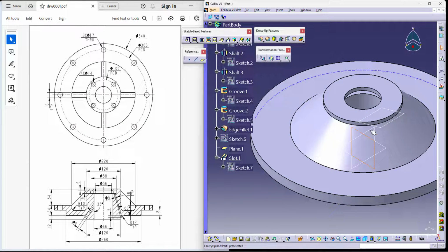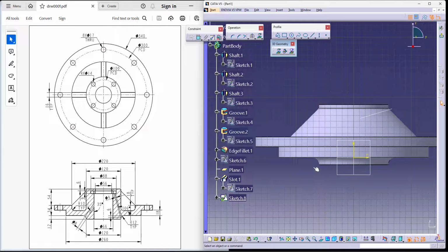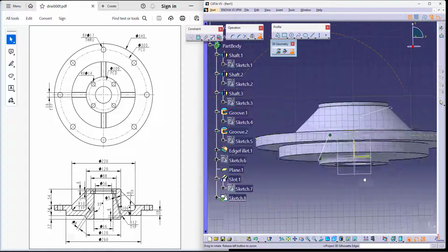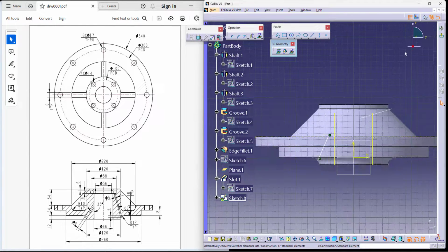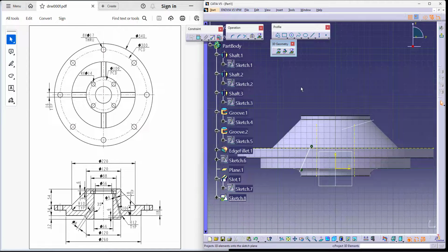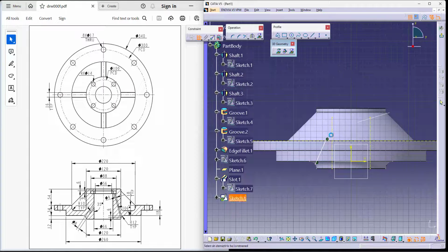Similarly, you have another one on the opposite side as well. You can pretty much do the same thing and go. I'm using my references at the moment. Similarly, I have the top face. It's stopping at the top face, so the top face is another reference of mine. Now I can simply make a sketch from here to here. This is actually in line with the inner circle. So let's try to coincide this onto that and then start giving a dimension, which is the angle.